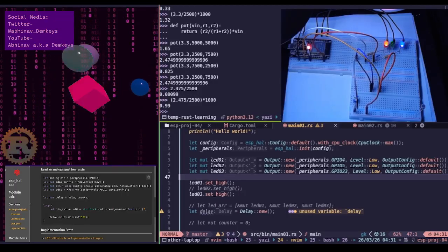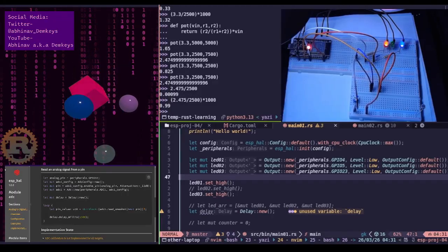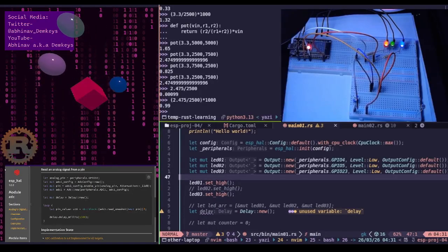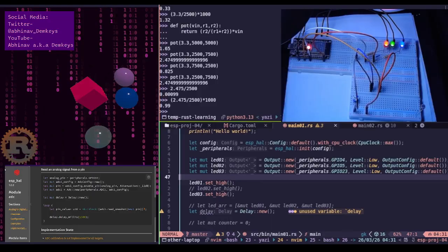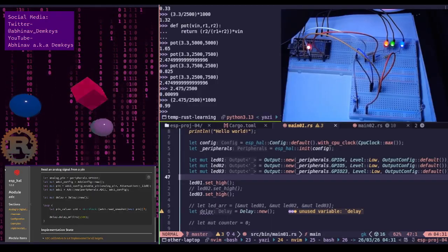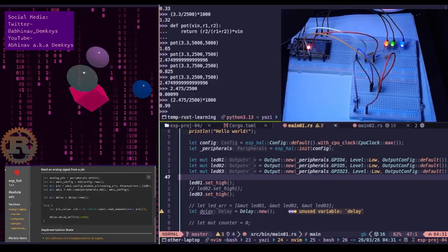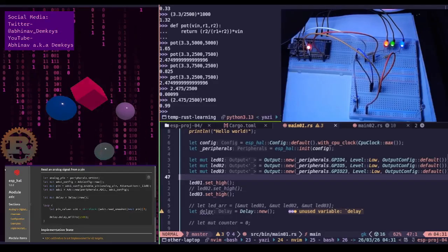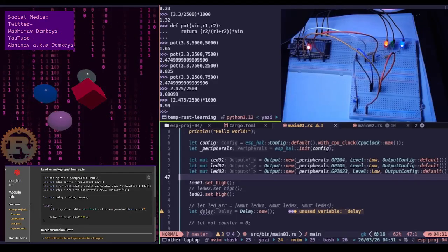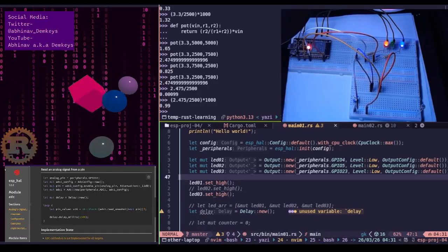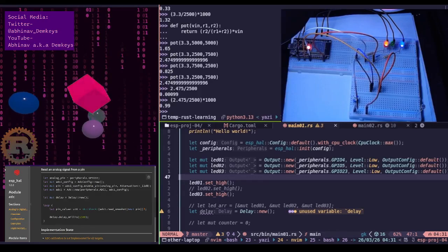The 1.1 volt ceiling. The ESP32 uses an internal reference voltage of approximately 1.1 volt. At 0 dB attenuation, which is the default, the ADC can only measure voltages between 0 volt and 1.1 volt. The problem: if you hook up a 3.3 volt potentiometer without attenuation, the ADC will hit its maximum.